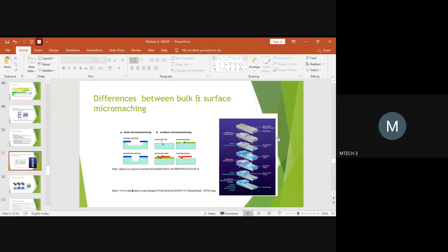So here you can see this is the substrate. Above the substrate, instead of adding an adhesive layer, a sacrificial layer will be applied. Once the sacrificial layer is applied, on that you will place the pattern which has to be retained by means of photoresist. This could be positive photoresist or negative photoresist. Later you will etch out.